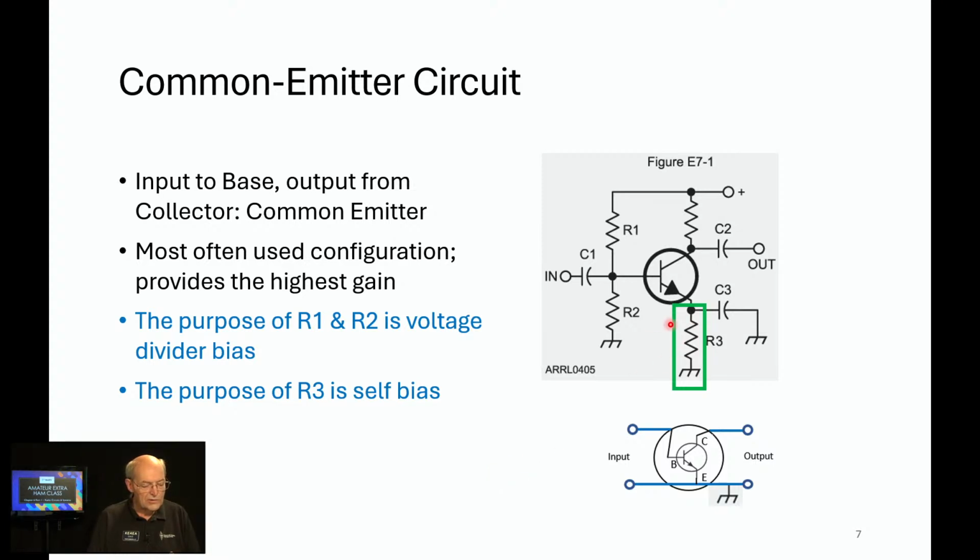So walking through the flow here, we've kind of looked at some of the DC aspects, the bias, the voltage divider. From an AC point of view, we're feeding a signal in here, and it's coming through a capacitor. The reason that we're using a coupling capacitor is that we don't want the circuit before this stage to change the bias conditions on the transistor. So as you may recall, a capacitor will not pass DC, it'll just pass the AC. So the signal will come through, it won't upset the bias that we've set on it. And C2 is the output coupling capacitor.